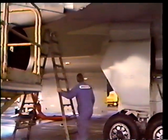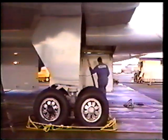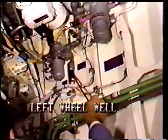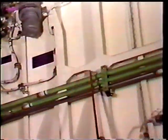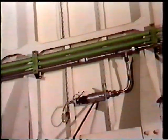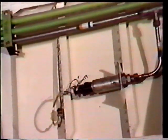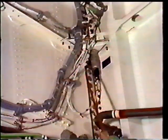Pressure transmitters for the left, center, and right systems provide electrical output signals for the quantitative pressure indication display on ICAS. The left and center transmitters are located in the left wheel well. The left transmitter is near the bottom of the mid-keel beam area, and the center transmitter is nearby. The right system transmitter is located in the right wheel well. The right transmitter is located in the corner of the aft wall and keel beam area.